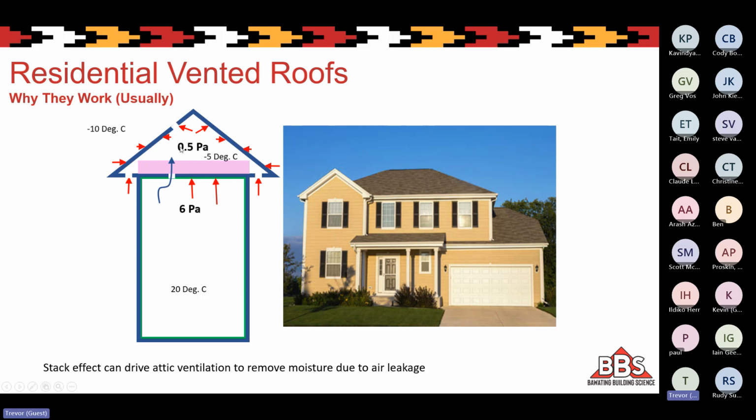And so even without wind, right? So remember we said wind can help with this, but sometimes we can't count on it. We don't know when it's going to be windy. We don't know which direction the wind's coming from. But this stack effect is only based on temperature difference and height. So it's always there to help us ventilate our attics.